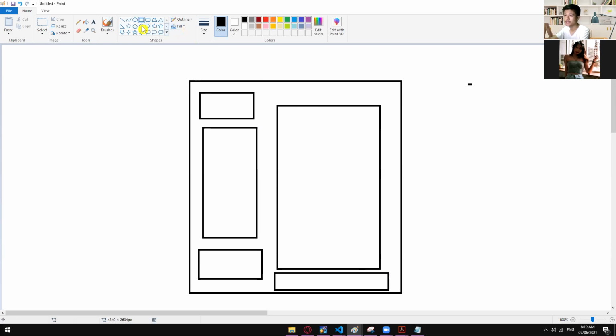Of course, you can deal with this one first, and then dissect that one into maybe two or three if you can still do it. And then of course you can convert this one into a different circuit, wherein, let's say, initially this one has a voltage source, and you can convert this one into a current source. So that is also possible. The good thing in transforming a voltage into a current source is that whatever the functionality of this one is, it's still the same. It just requires a different source. Before it was voltage, but right now it requires a current source.